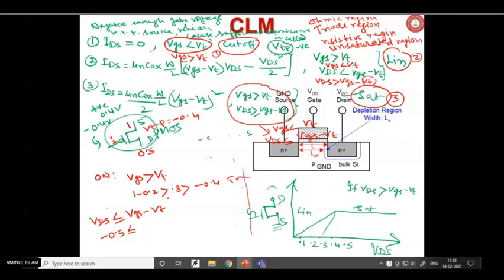And now I am asking the question for PMOS, not NMOS, P MOSFET. Let me try it again. I'm drawing this P MOSFET. 1 volt is here, and 0.5 volt is here, for example, and VTP equals minus 0.4, and this is 1 volt. Body is also 1 volt. Gate is 0.2 volt, say. So in which region is it operating? That is the question.